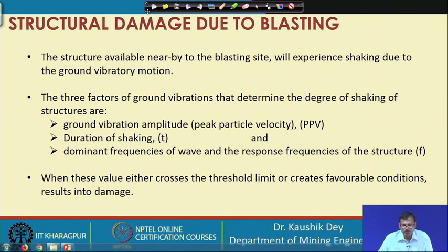However, in blast vibration most of the cases the amplitude is also high, but not that high as it is observed in the earthquake, and the duration of shaking is almost negligible if you compare it to an earthquake, because most of the ground vibration generated from the blasting is generally damped within 1 or 2 seconds, and the frequencies generated by the blasting wave are always high frequency.